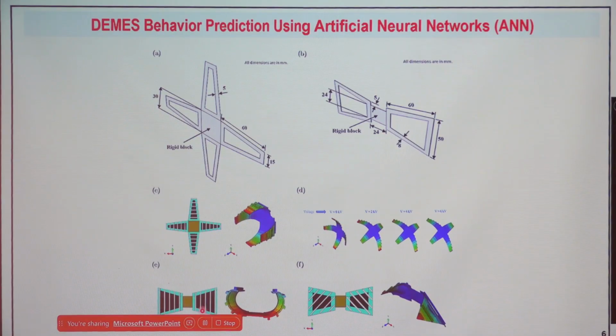We have already seen that the spacing between the consecutive stiffeners has an effect on the attained initial configuration and final configuration. The third parameter is the orientation of the stiffener. When you change the spacing between the stiffeners, the number of stiffeners will also change. If you increase the spacing, the number of stiffeners will reduce. If you keep a small spacing, the number of stiffeners will keep on increasing.